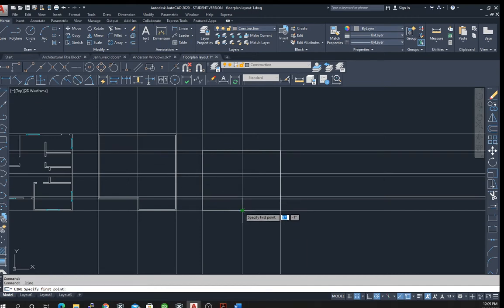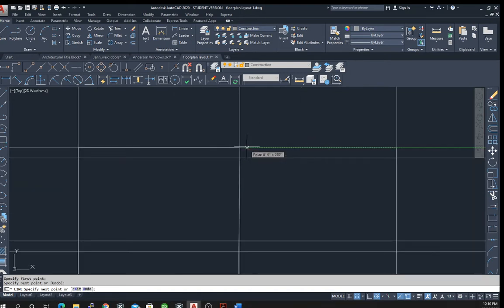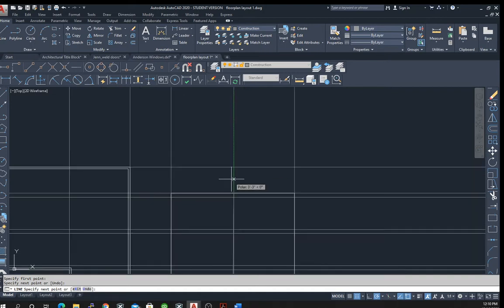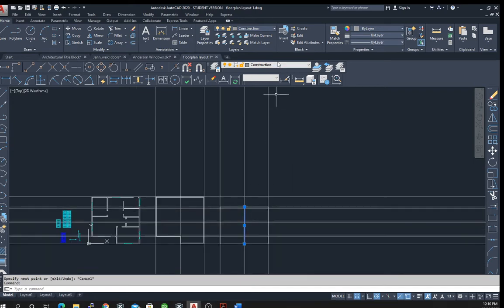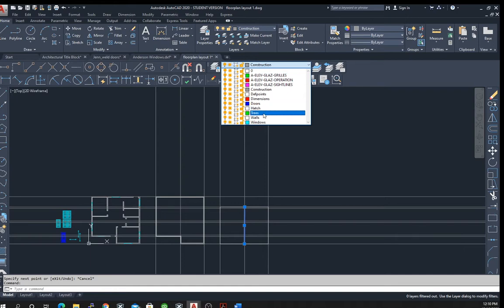And then we're just going to draw the line in. So we're going to draw it from this intersection right up to that intersection. Now, here's one thing I can't explain to you. I don't have an answer for that. If you see as I draw this line, it very easily finds that intersection. But you could see that sometimes when I drew, although actually I didn't put that in. I did put that on the construction layer, but we'll change that. But you saw when I was drawing the other lines, it didn't easily find the intersection line. I don't have a good explanation for why AutoCAD does that.